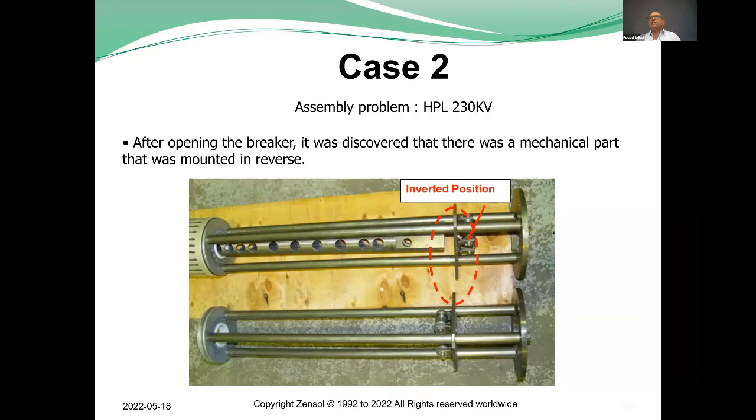So when it's changed, there is something wrong. So the sound, which is exactly like a vibroacoustic signal, gives us what we call the fingerprint. So the signature, the typical signature, we know it, and then after we compare it to the new signature. So with this comparison, it's easy to find problems.